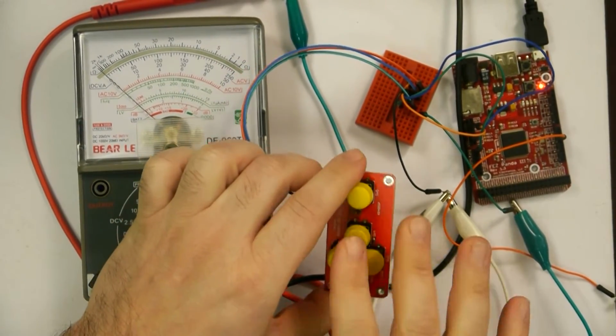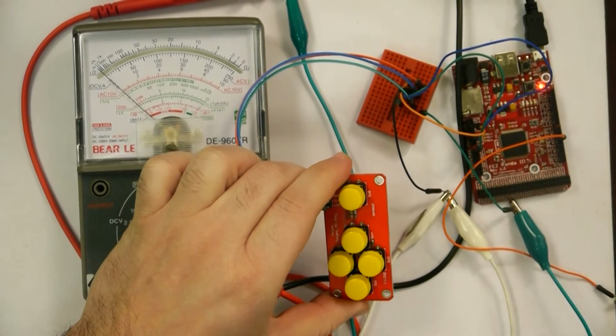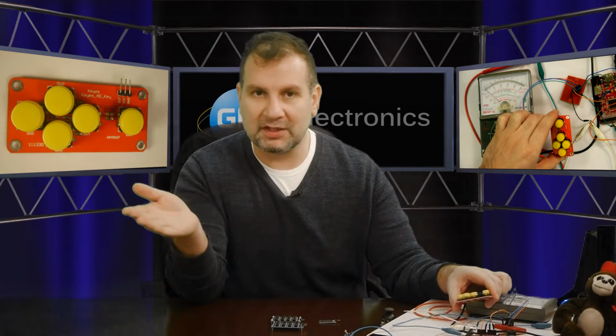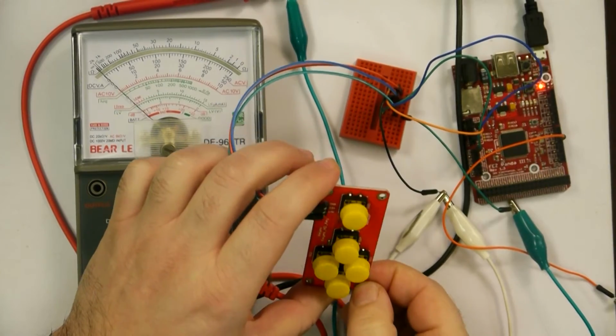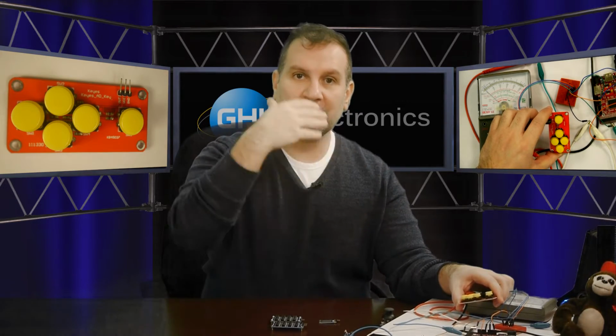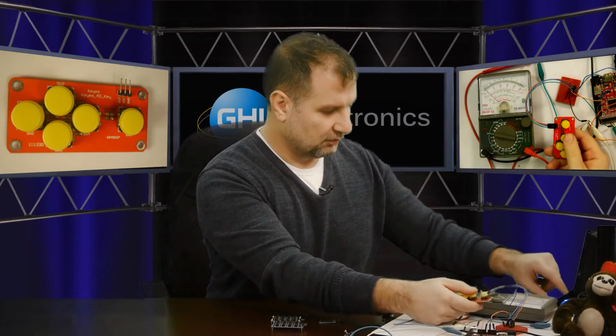So let's say you have multiple buttons, but you don't have that many digital pins, or you just don't want to wire, let's say in this case we have 5 buttons. Is there a way that you can read those 5 buttons without having 5 wires, like 1 to each button? Yes. Each one of these buttons is connected to a resistor, and the resistors are up around these buttons, and each resistor has a different value. So each button pressed will connect a different resistor on the wire, causing a different voltage to output. And then you can measure these voltages, and you can determine through the voltages that one of the buttons is pressed. And well, we can see that as well.